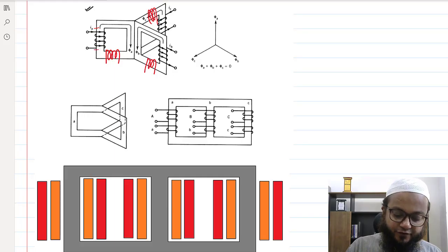So obviously if you see this section here, if I energize it from this source, let's say a current source here, the flux produced by it will actually see the reluctance path here as well, and here as well, but the minimum reluctance path would be the one nearest to it, and most of the flux will go through this branch, right?